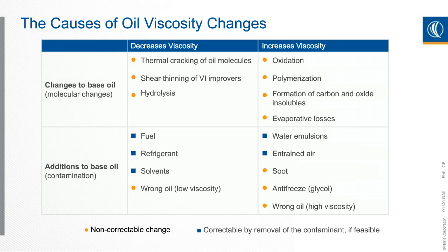Is there potential for one of these contaminants to be introduced? Is there potential for oxidation occurring because of what you see in the RULER test or the RPVOT test or acid number test? All these things need to be looked at in tandem so you have a better ability to conclude what's happening to your oil.